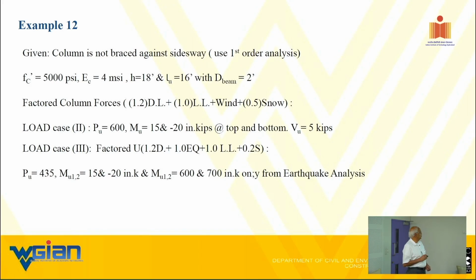Load case 2, this is a combination. For load case 3, this is the earthquake combination, for example. And this is a no earthquake type thing, and that is dead load, factor that, live load, factor that, wind load, and snow load.